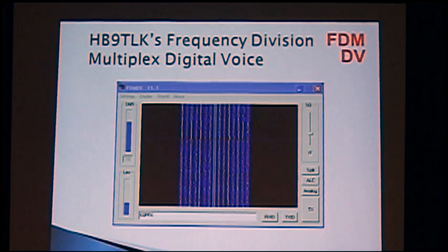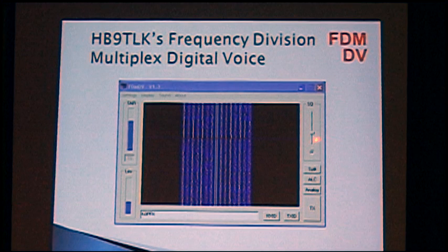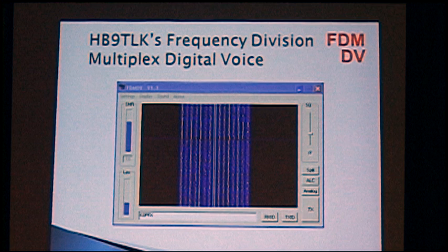But anyway, this has been a very good program, and it's very simple to use. This squelch control over here will allow you, even if you have some dropouts, to come through, because if you can catch a few syllables of a word, you can probably understand what the fellow's saying. This would be in very low signal-to-noise ratios. You have short message service down here up to 55 characters.